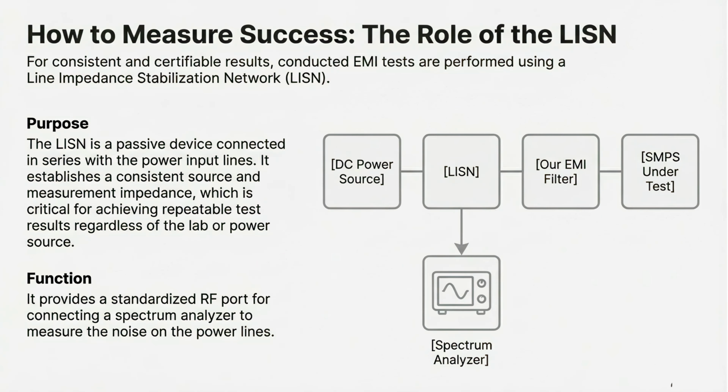To achieve consistent and certifiable results, conducted EMI tests are performed using a line impedance stabilization network, or LISN. The LISN provides a standardized measurement impedance for connecting a spectrum analyzer.